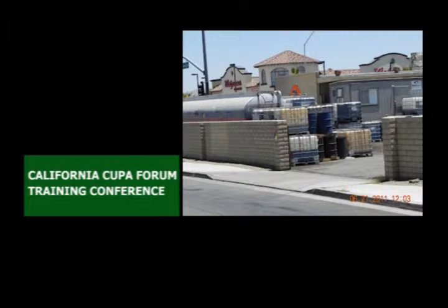But that doesn't matter, because if you're an inspector or you're this facility, what do you want to see in the plan? You want to see the topography. You want to see the grading. You just don't want to have somebody say, yep, it's adequate. So if you're this facility, I would have a topographic drawing. I would make sure, yeah, this is where it drains to. I would verify that. And just to keep idiots like me from stopping, I would put in a berm here, just a rollover curb. And that's what it sounded like when that guy chased me down.